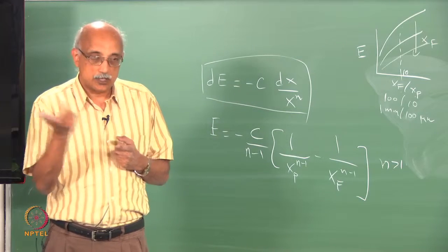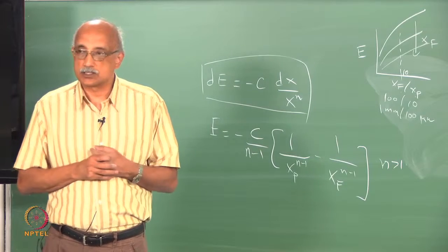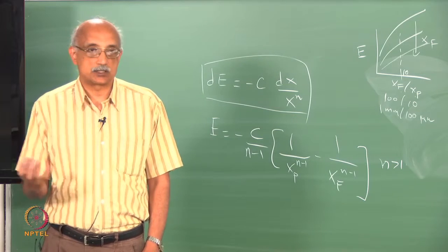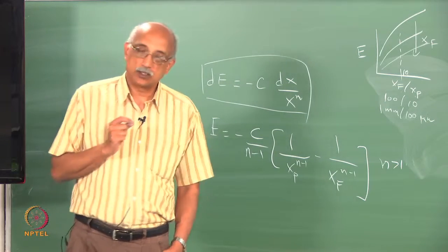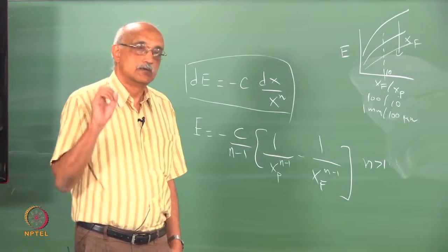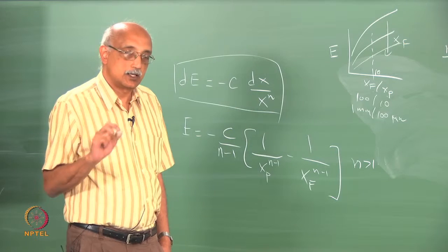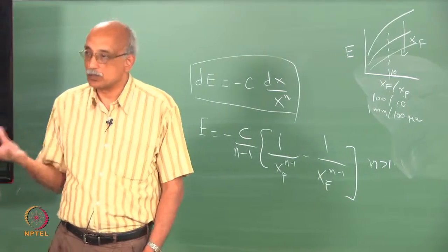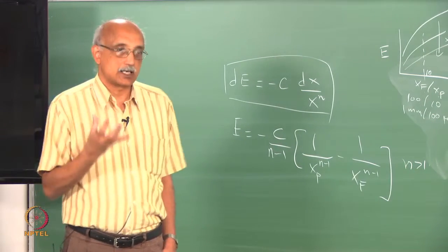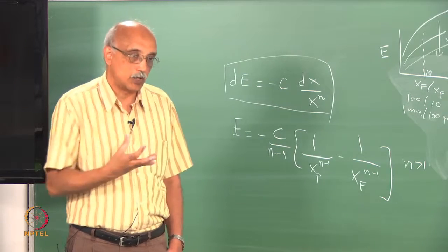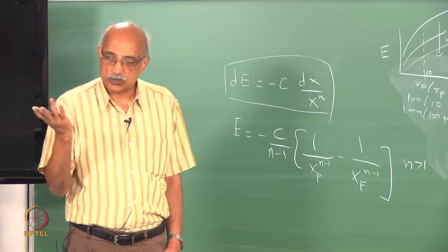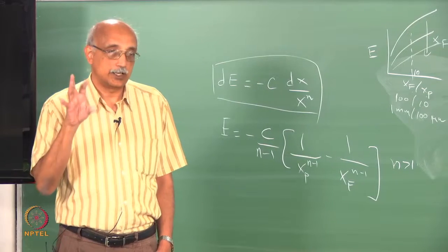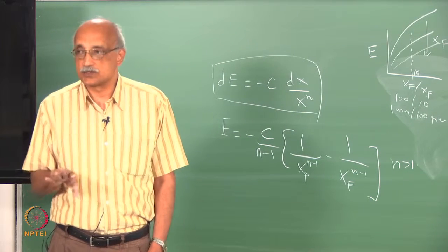There are very few mechanical size reduction operations where this principle is violated. One of the techniques, which we talked about a little bit in one of the earlier classes, uses acoustic energy as a way of reducing size. In that case, what you are relying upon is a direct interaction of a shock wave with the material whose size you are reducing. Because that technique relies upon the interaction of an imploding bubble with the particle in suspension, it is much less size sensitive compared to methods such as ball milling. In fact, I think I showed you a graph in that lecture on the energy efficiency comparison between ball milling and cavitational size reduction.